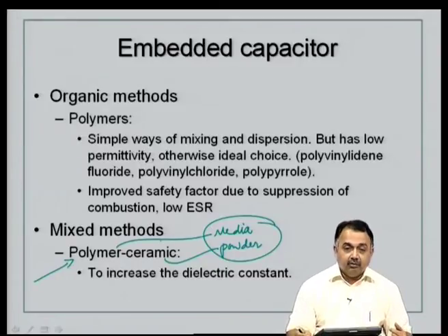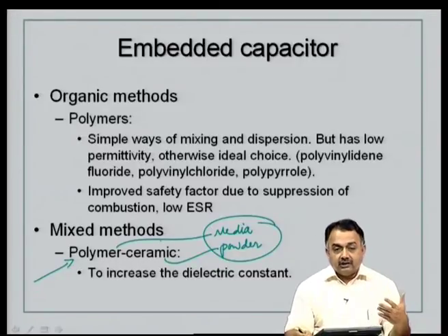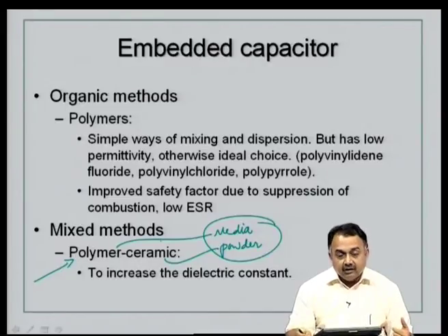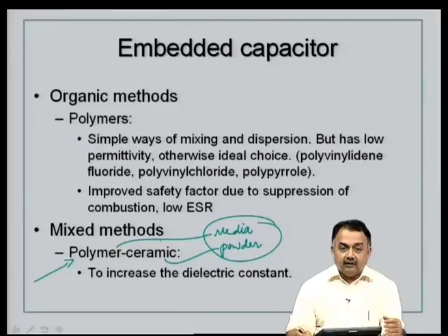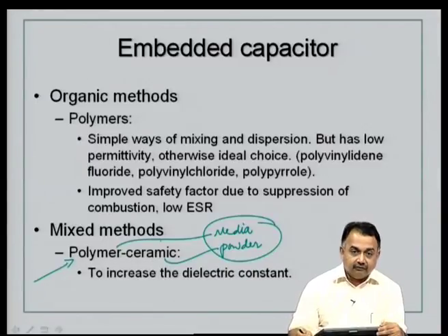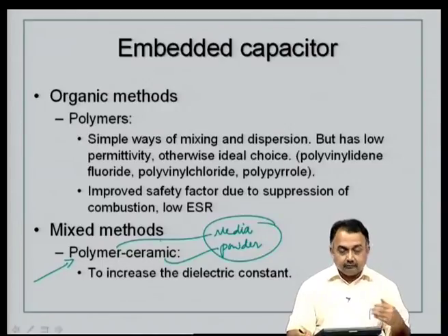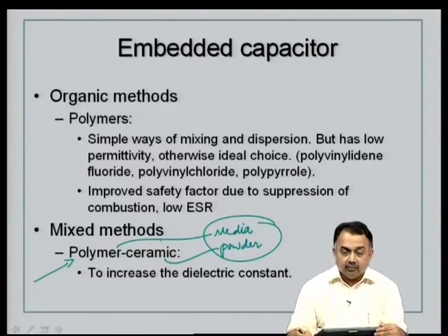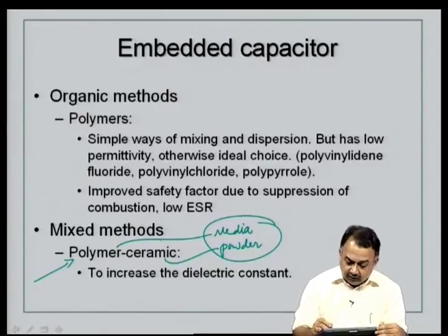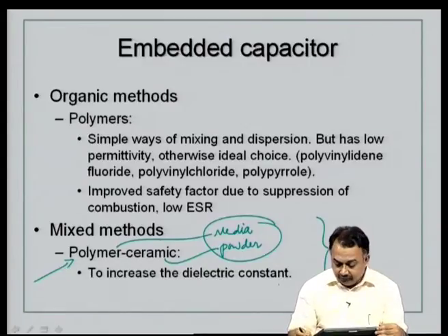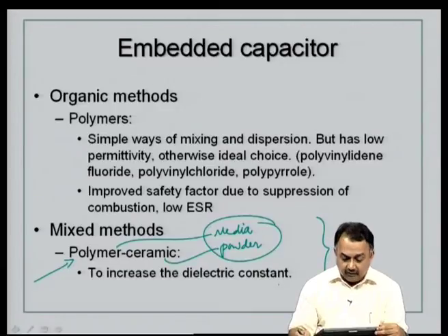Then on this polymer ceramic cured material, you can either laminate a capacitor foil, or you can deposit copper by electroless plating followed by electroplating methodologies. So, this looks very familiar and has a high possibility of integrating with the printed wiring board technologies.